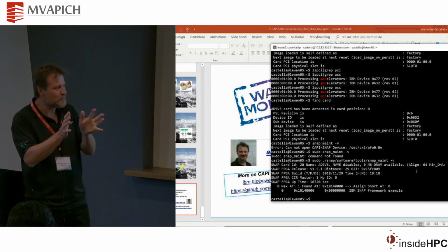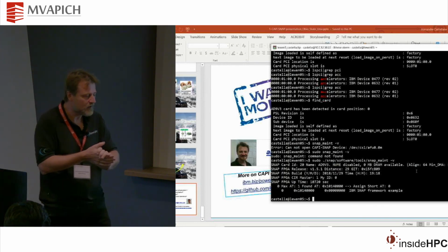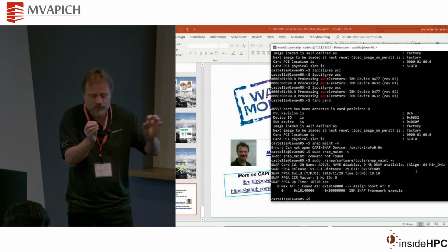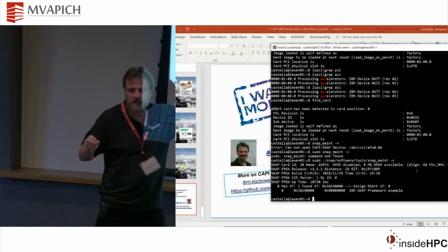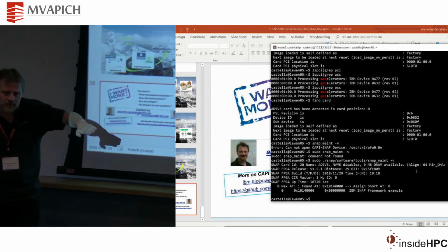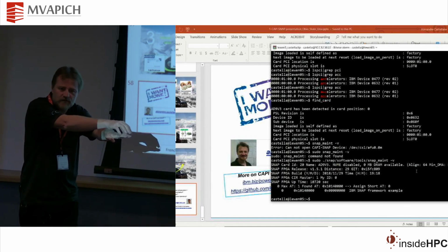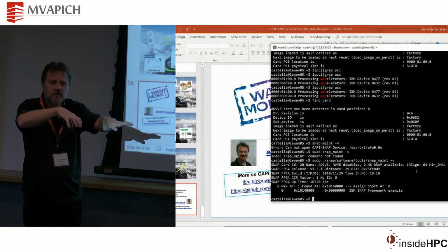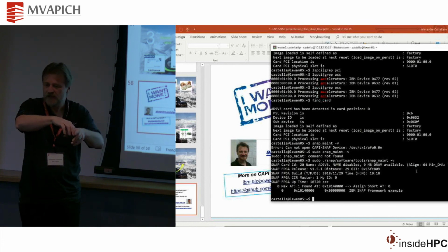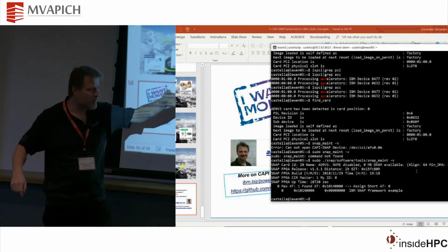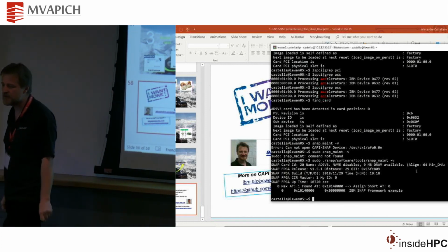So you build a chip in, let's say, 1 or 2 hours. Once you get the binary, we have a tool. Once the card is recognized, we can push the binary into the memory of the card, and at next power up, the binary in the flash will program the newly defined function that you want to put in the FPGA. It will still be recognized in CAPI mode, but then your function will be present and you can play with it.